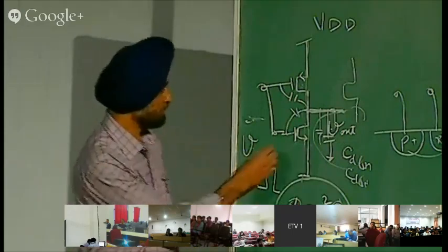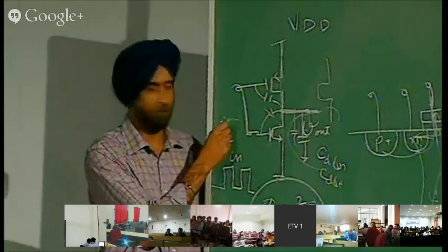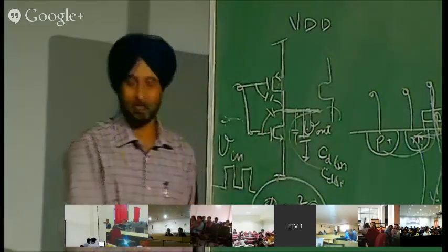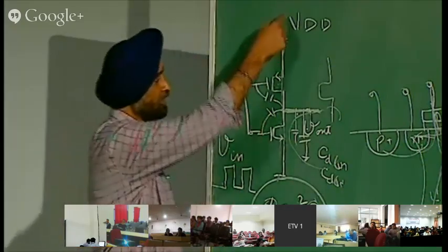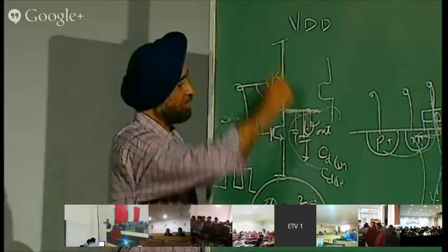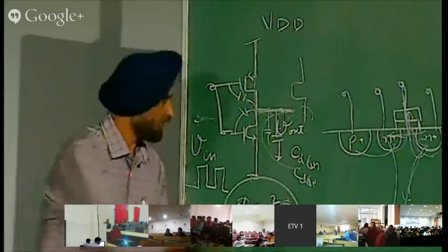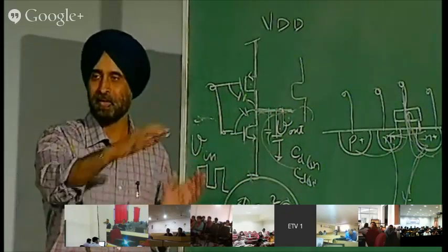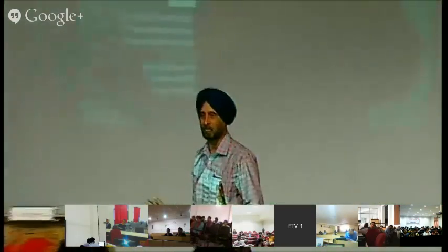Okay, so when we change the signal here, when we change the voltage here, it also needs to be changed. So there is a capacitance. You have to charge the capacitance or discharge the capacitance. Charging occurs this way, from VDD to here, discharging occurs this way, onto ground. So to charge or discharge these nodal capacitances, there may be a big circuit. At each node there are capacitances. To charge or discharge those capacitances, you need active power.